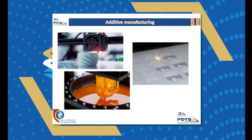That can be done with the next process, which is selective laser sintering, and that is the image to the right. How selective laser sintering works is powder is inserted into a bed of a 3D printing machine. The powder is then melted down at specific points by a high power laser.